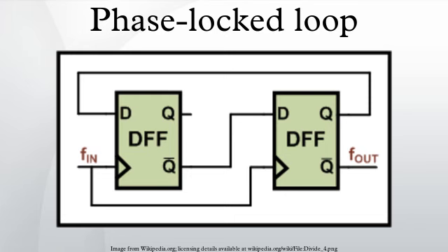Frequency multiplication can also be attained by locking the VCO output to the nth harmonic of the reference signal. Instead of a simple phase detector, the design uses a harmonic mixer. The harmonic mixer turns the reference signal into an impulse train that is rich in harmonics. The VCO output is coarse-tuned to be close to one of those harmonics. Consequently, the desired harmonic mixer output falls within the loop filter pass band.